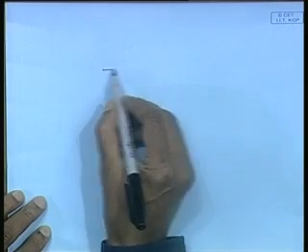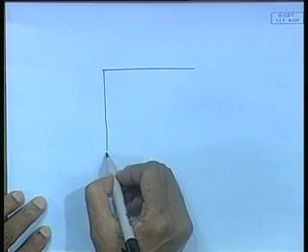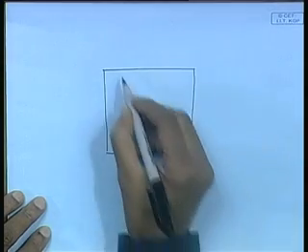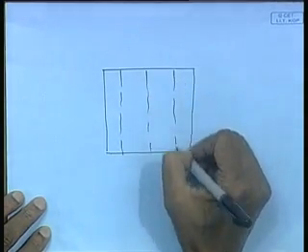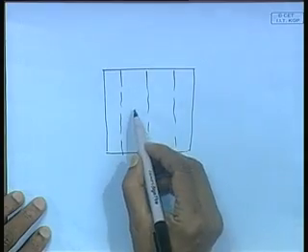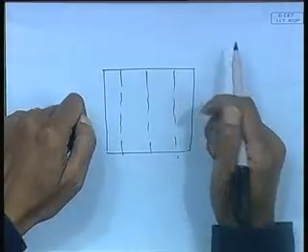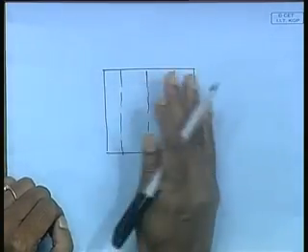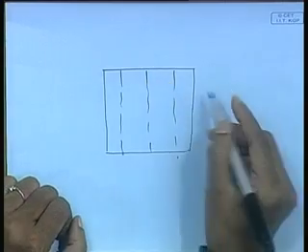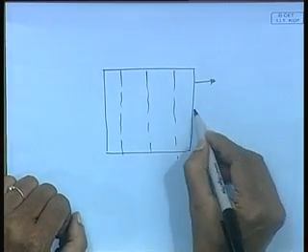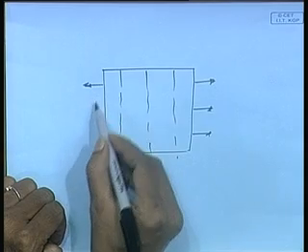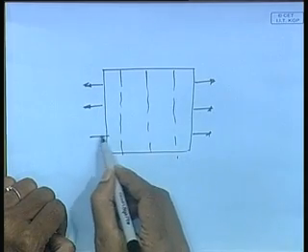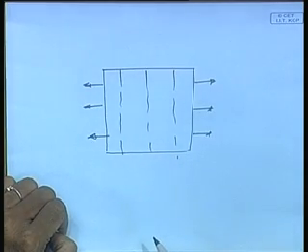It is like this: you have the plate, say the stiffeners are to be welded in this direction, right. So, it tends to buckle in this plane, right. If I can provide a tension force, then this buckling will be prevented.